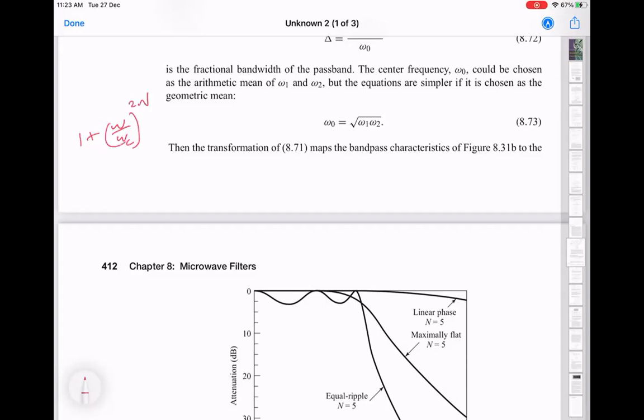like this, right? So omega or omega c, once you fix n, how much insertion loss you're going to get at a particular frequency omega is going to depend on how much omega is with respect to omega c. For example, if you had n equals 2 and you had 4, at omega over omega c equal to 1, insertion loss is 2.